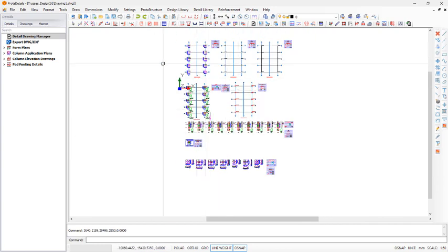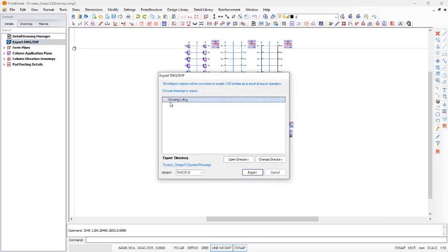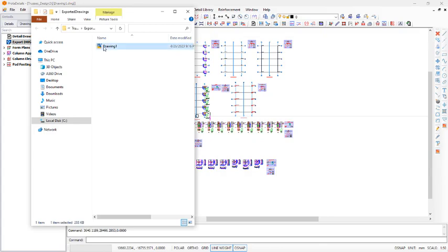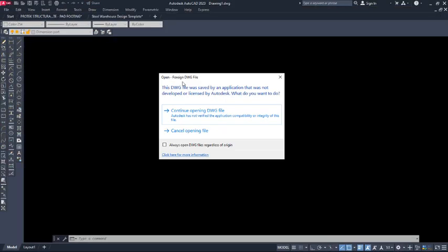All right, after which we'll be exporting the whole of this to AutoCAD. So you click on this, right click, then click on export right there. We'll be leaving the name as drawing 1, and then we'll choose the lower version of AutoCAD, 2007, and then click on export right there. This is going to export and open the file directory, so we can double click on it so that it will open in AutoCAD just like this.